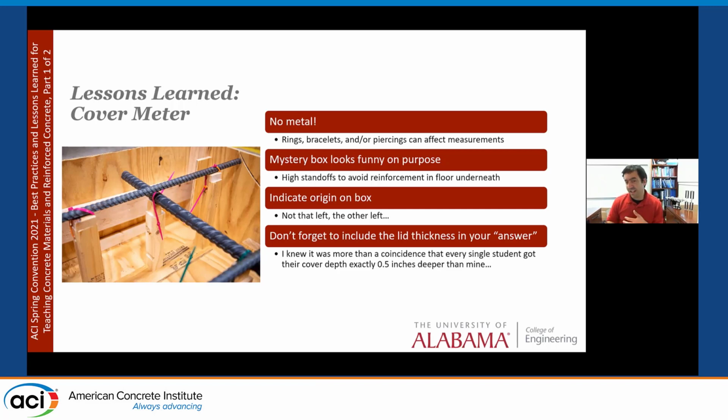So the standoffs here are about, I think, 9 inches off the ground, just to make sure there's no undue influence from whatever surface you're resting the box on. This was actually the biggest thing. I originally made the box and just had the rebar sitting down on the bottom of the box. And when I put it on the concrete floor, it was picking up rebar from the floor. So you want those high standoffs.